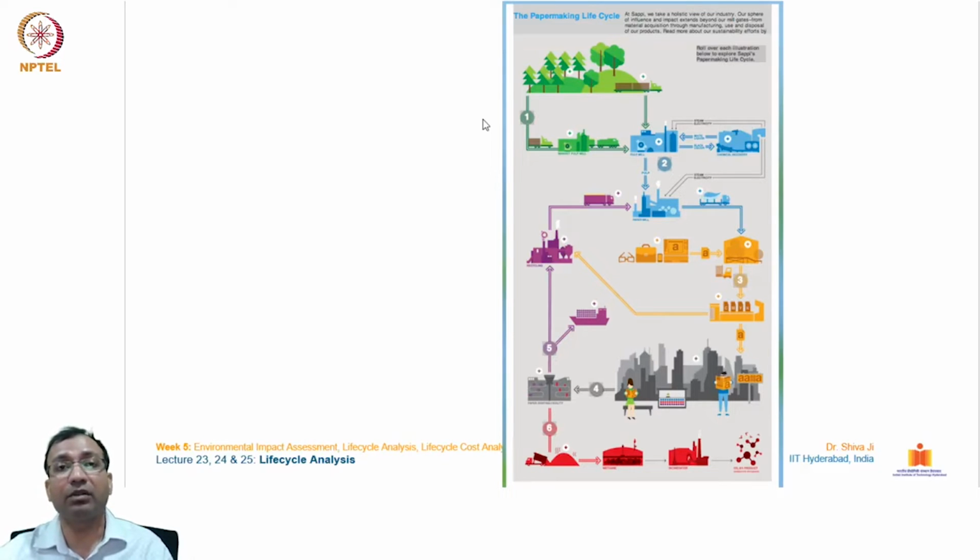For example, I'm talking about the lamination which happens on these papers. The lamination process installs a thin layer of plastic on the paper with a heat-pressing method, and at the end of the life cycle, it becomes very difficult to take these two components apart, because it uses adhesive also.